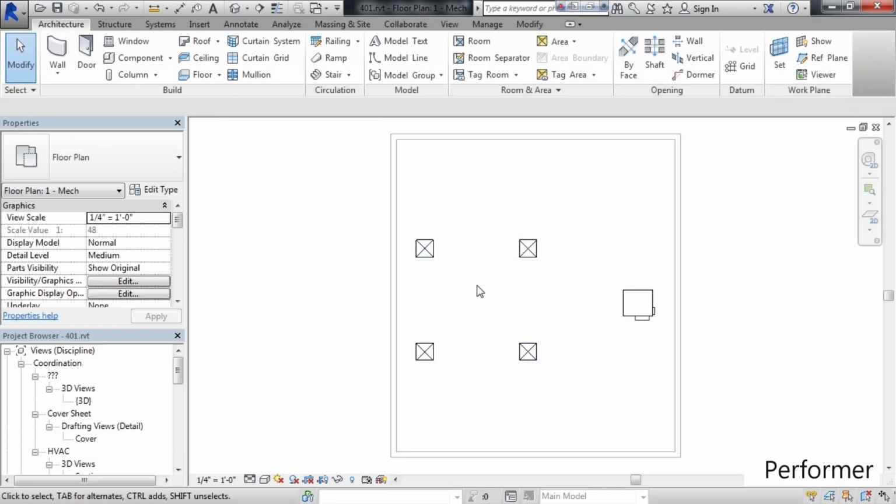So as a review, we looked at some basic fundamentals of how to select objects, components, different things in your Revit project. One is we just click on them with the left mouse button. Another method is we drag a window either to the right or to the left, one being a crossing window, one being a selection window. We also select something and then right-click and choose all instances in the view or in the entire project. And the last method we looked at was selecting previous elements.